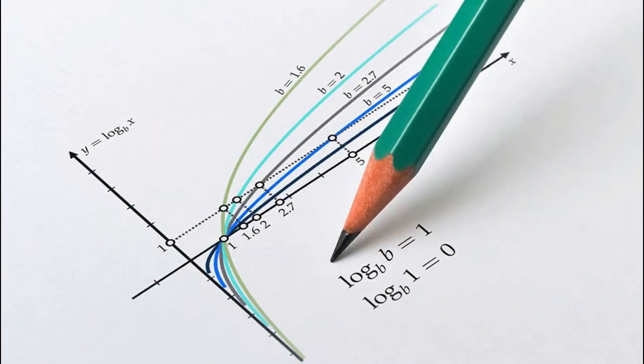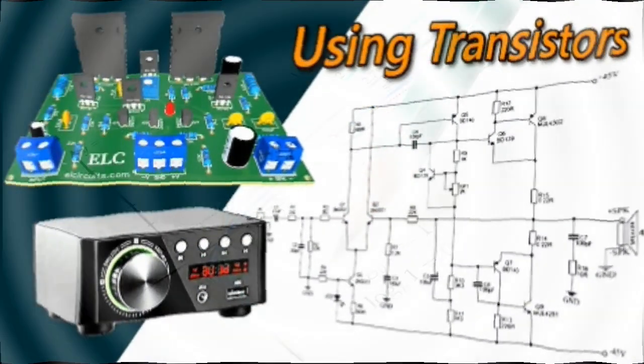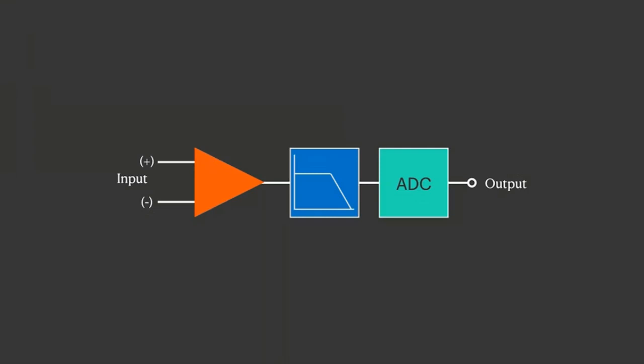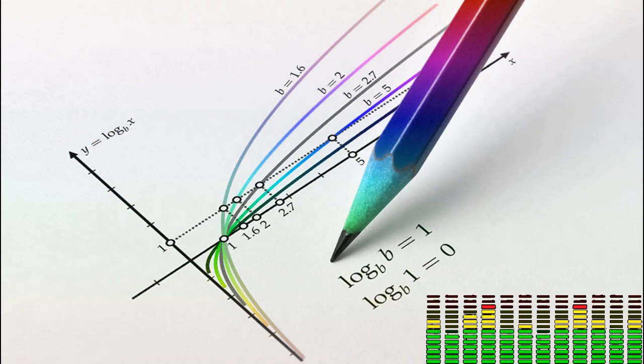Since the voltage and current gain is 20 times the logarithm of the output to input ratio, the power gain of the amplifier is 10 times the logarithm of the output to input ratio. However, due to the logarithm, the power of 20 dB is not twice that of 10 dB. Also, a positive dB value indicates amplification and a negative value indicates attenuation.